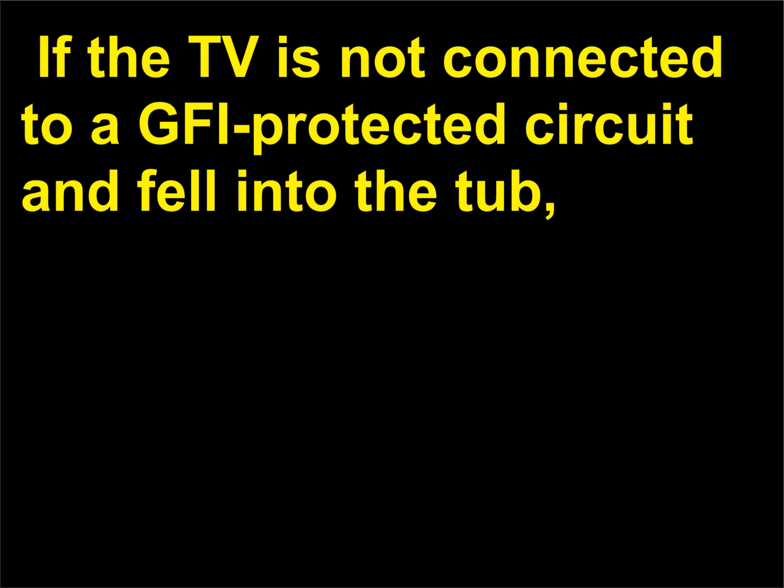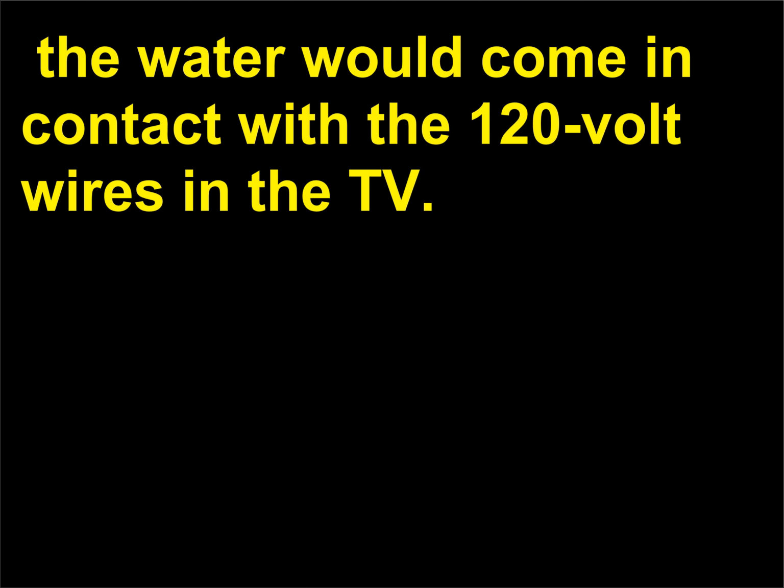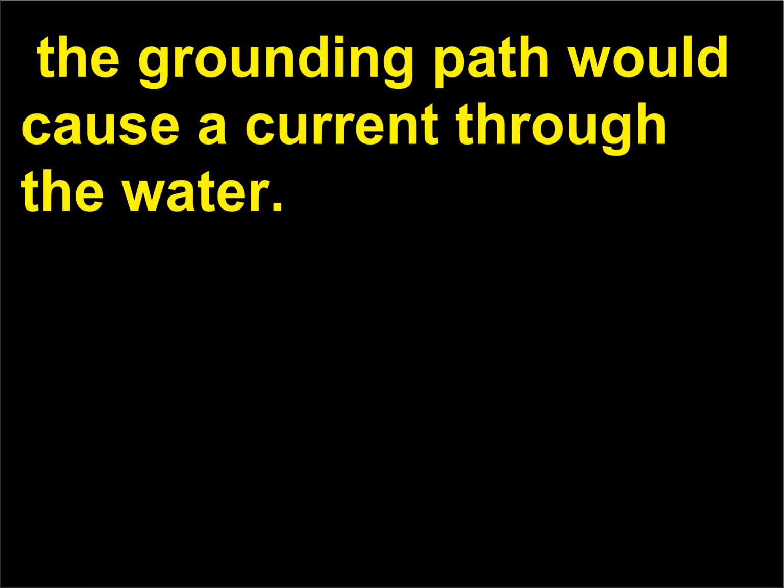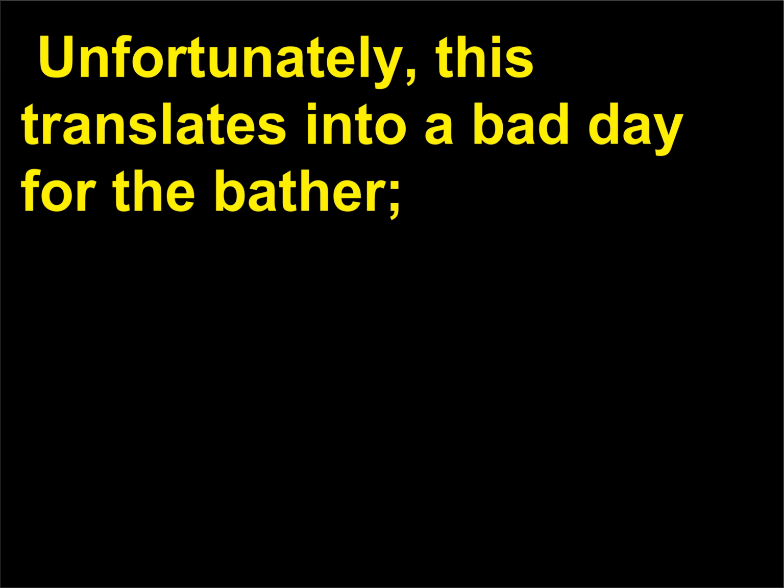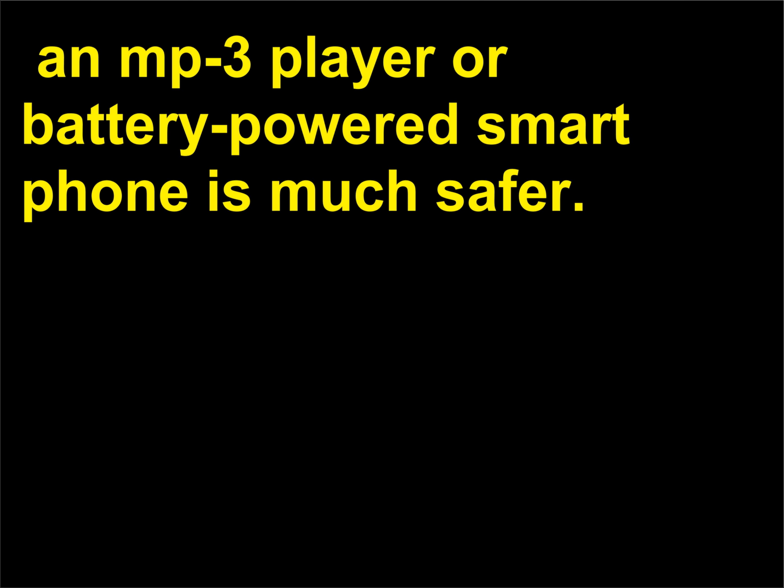If the TV is not connected to a GFI protected circuit and fell into the tub, the water would come in contact with the 120-volt wires in the TV. With the metal plumbing of the tub connected to ground, the grounding path would cause a current through the water. Unfortunately, this translates into a bad day for the bather. An MP3 player or battery-powered smartphone is much safer.